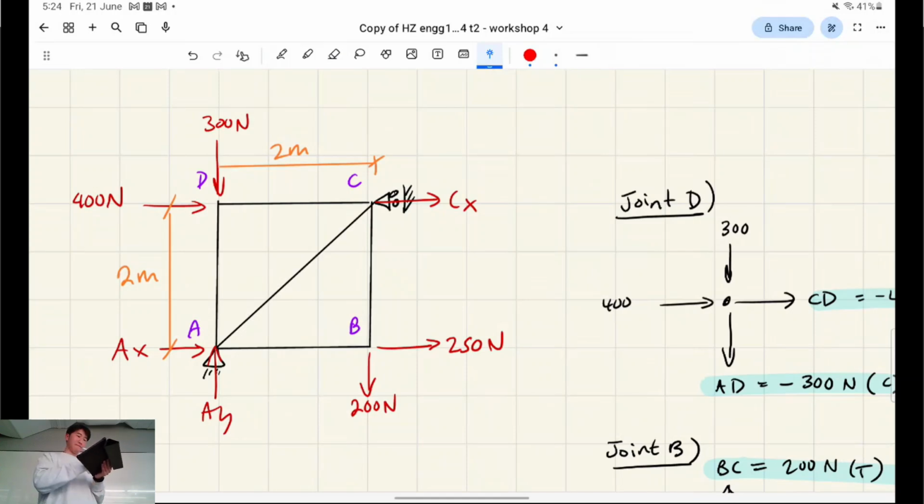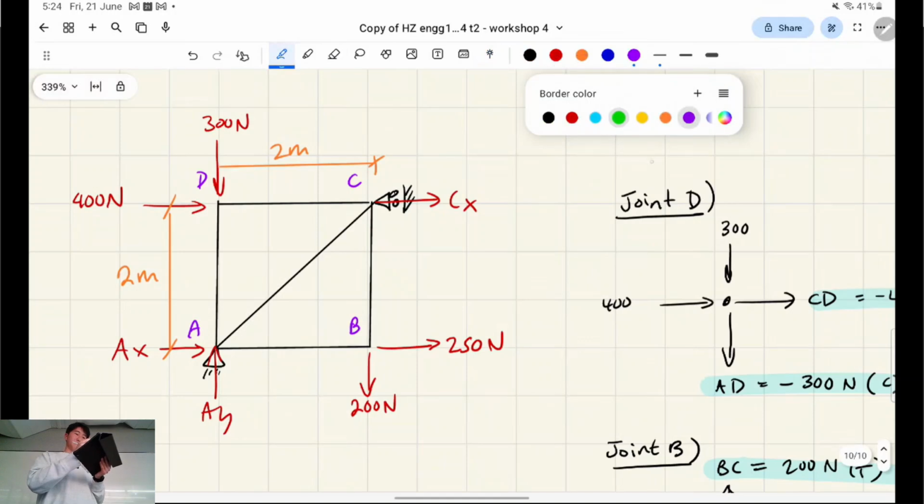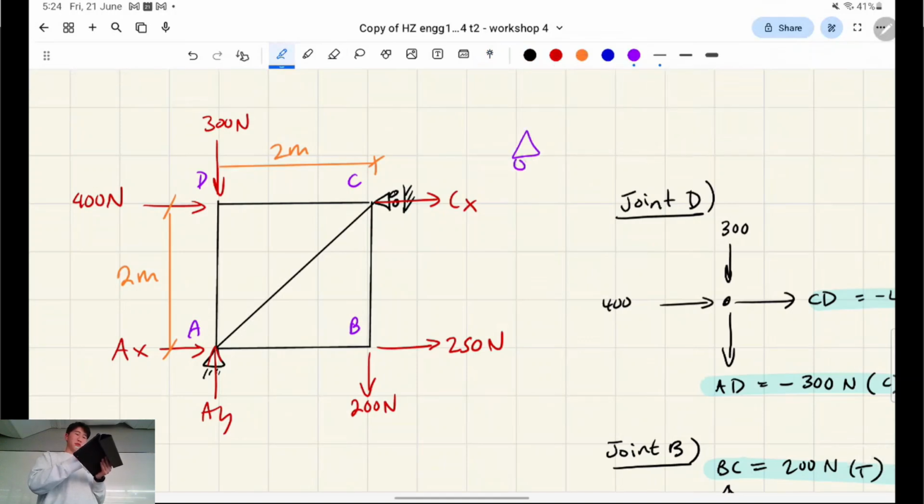That's right. Like what you said is correct, but remember with the roller support, it resists normal forces, but not tangential forces. So the fact that this is on a vertical surface instead means that it's free to move in the tangential direction. That's the way you want to think of it. Because what happens if it's on an incline? Do you know what I mean? Right. Yeah, you would have a different case, and then you'd have to have a better understanding of how these reactions work, right? But yeah, no, you're completely right.